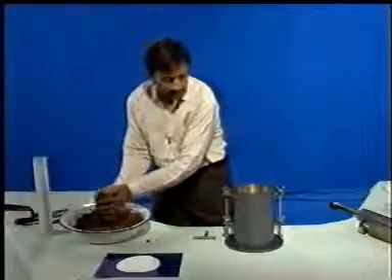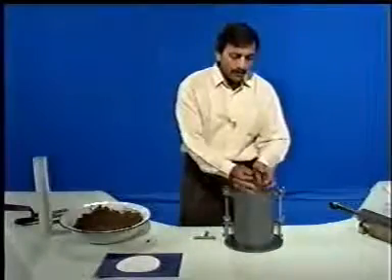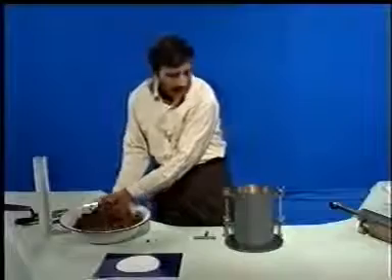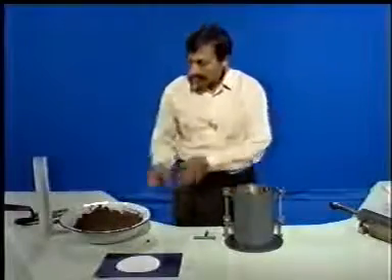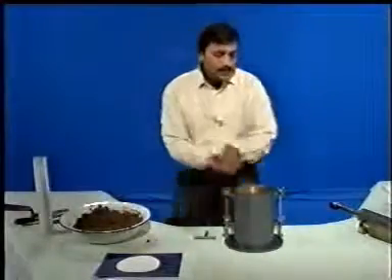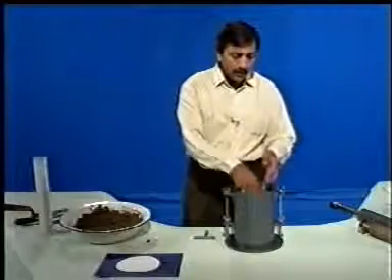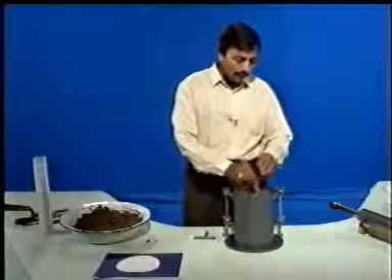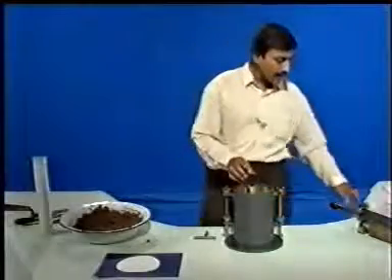Transfer the soil into the mold and fill such that after compaction the layer is about 1/3 or 1/5 of the total thickness, as the case may be.